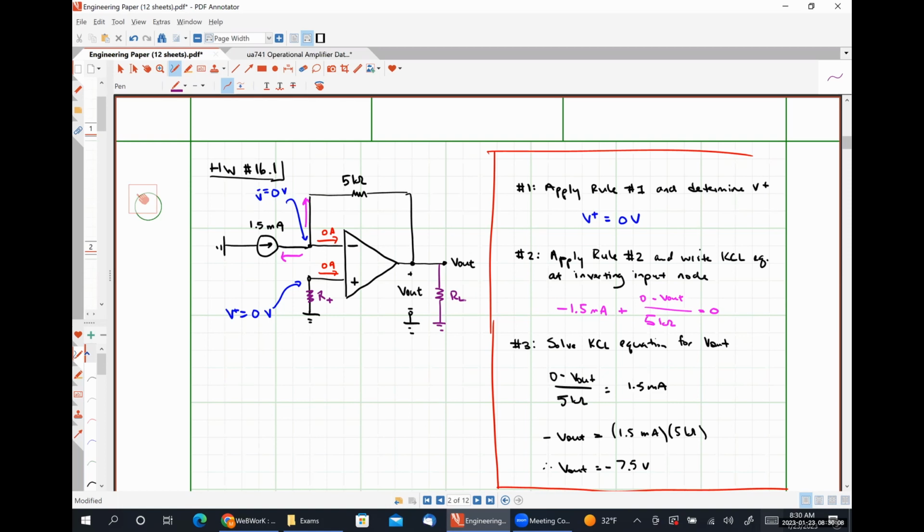Okay. Meaning that our circuit analysis would not change at all, even if that resistor RL were there. Okay. The only resistor value that would change our analysis would be if RL were 0 or a direct short circuit to ground, which would obviously force V out to be 0 because it would be connected to ground with a wire. Okay. So these are two resistors that you might see in circuits that you're asked to analyze.